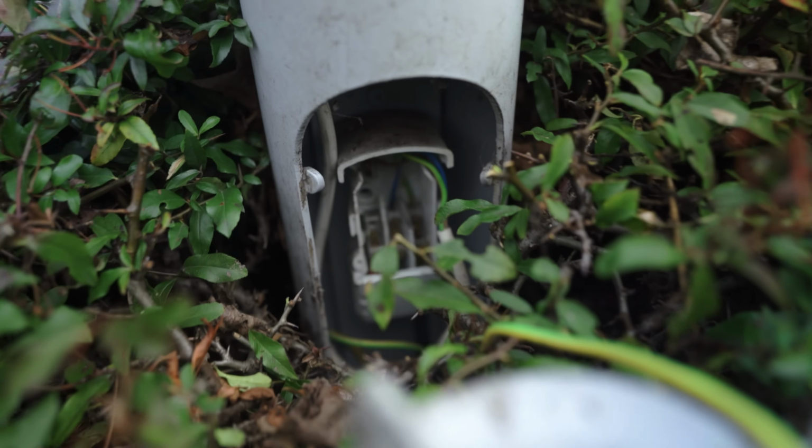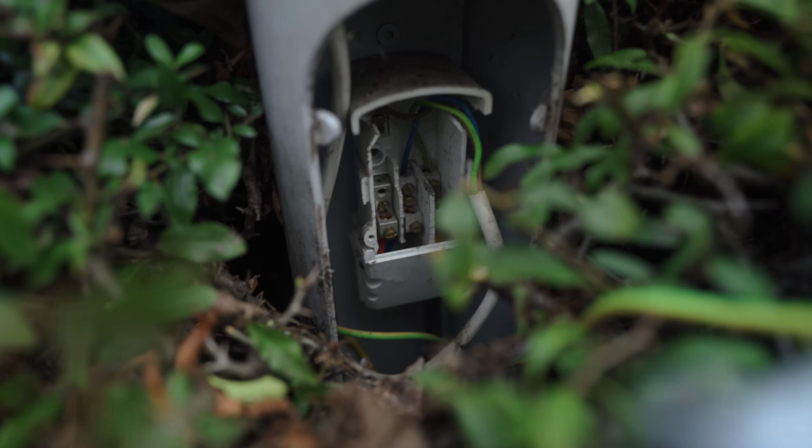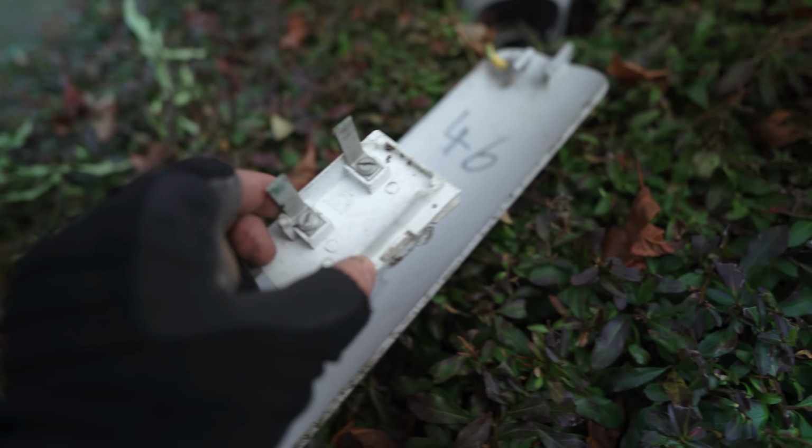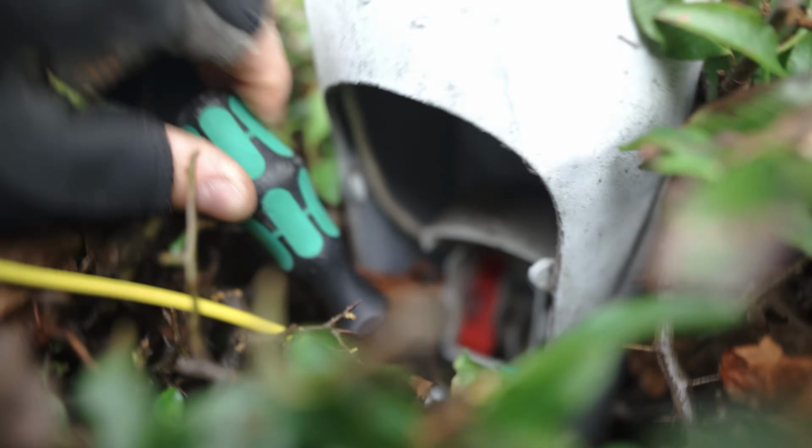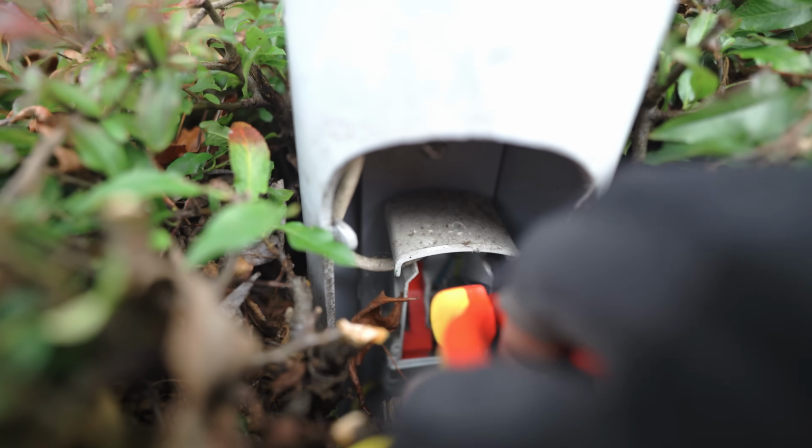But yeah, let's go bang these fuses in anyway. Just because I want to scratch an itch and see which one is the offending lamppost. So this is the first of the two that were probably causing the fault. I think I'm going to leave this one because it seems okay. The one that's most sus to me is this one, the one with the rewirable fuse wire. Just tested with the neutral and earth disconnected from that lamppost, and it's still around 1 megaohm, so that's not the issue there, to be honest with you.